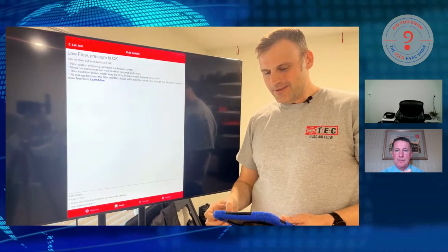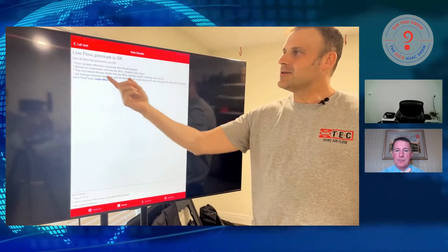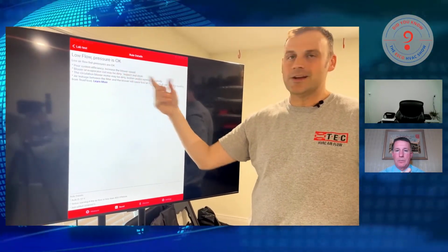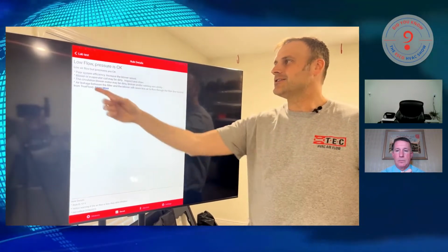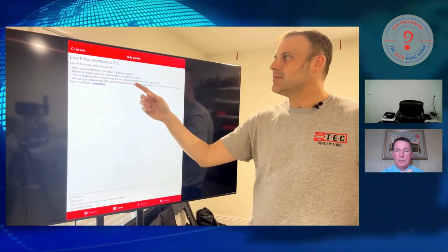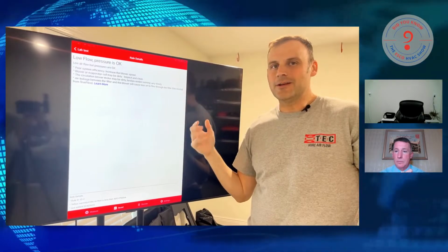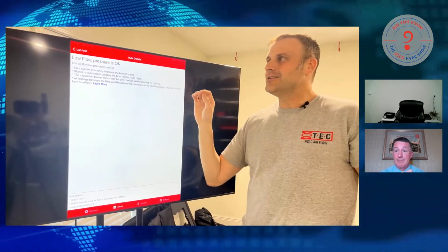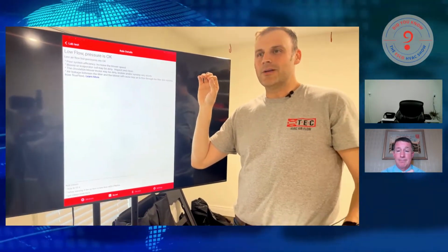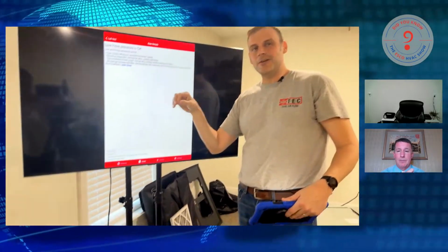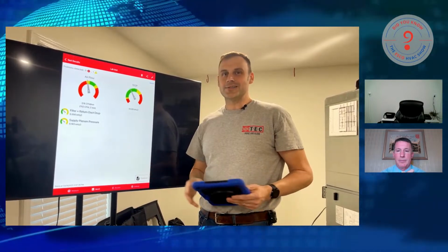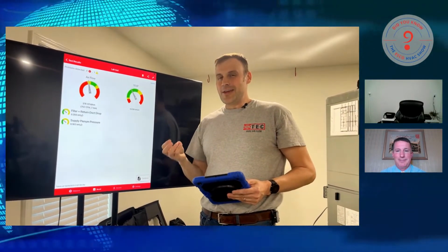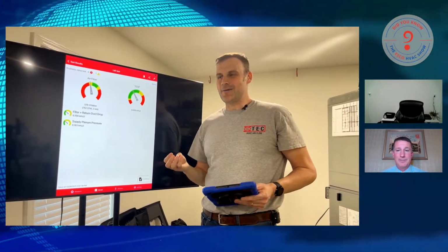If you click details, low flow pressure is okay. Poor system efficiency, increased blower speed. Blower or evaporator coil may be dirty, inspect and clean. The circulation blower may be dirty, broken, and or running very slowly. What I'm getting at here is we've taken a lot of time to pour in what we think are all of the faults that would cause any one of those dials to turn yellow or red for every air conditioner. Whether it's when you get to heat mode's coming out.